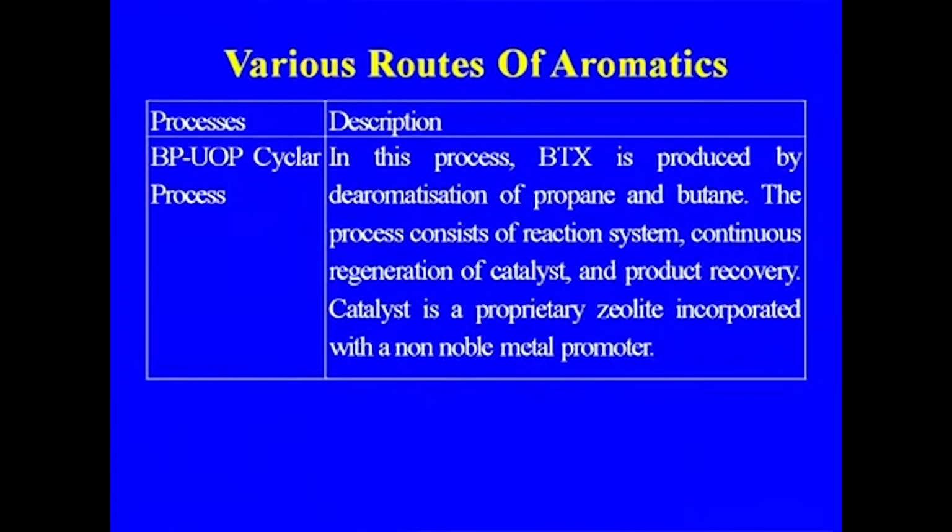And another process, which is one of the commercial installations, is also there in, I think, Nigeria. In this process, BTX is produced by de-aromatization of propane and butane. The process consists of the reaction system, continuous regeneration of the catalyst and product recovery. The catalyst is a proprietary zeolite incorporated with a non-noble metal.